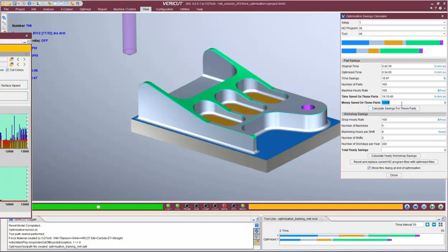To get a better view, you can extrapolate that over your entire operation of shifts. So here we have 5 NC machines running parts like this, cutting titanium metal, for example, and if we optimized all those parts, those machines ran at 8-hour shifts, and this shop has 2 shifts running. Here's your number of average work days, and just calculate the yearly savings. 350,000 plus on this particular type of part. As you can see, force optimization will pay for itself normally in less than a month.